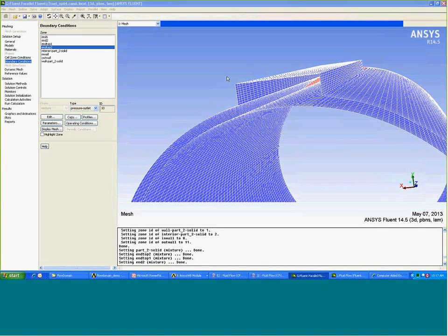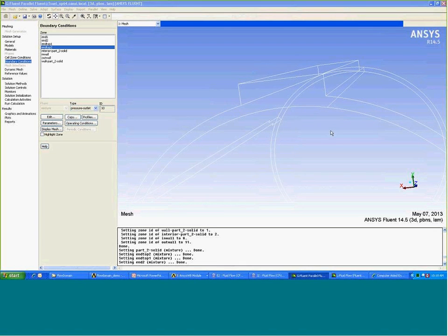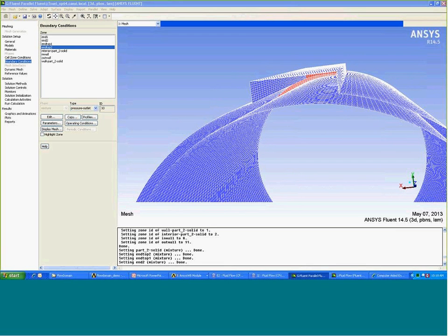In a similar way, because the contacts are detected automatically because of the flow-through mesh and multi-body parts, multi-bodies in a single part, Fluent can also identify the surfaces where the three volumes come into contact as internal elements. Again, Fluent will take that as internal nodes and elements, and you do not need to do anything additional for these surfaces that you can see here. There's no wall boundary right here on this surface or on these two edges.